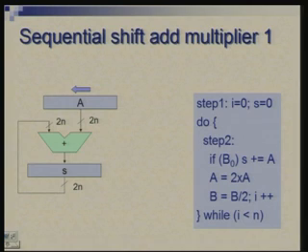So, the operand initially is placed in the right half, and it keeps on shifting to the left, and by the end it has reached the other end. This is the key part of the circuit, and to control this, we require another register holding B, which will experience a right shift.